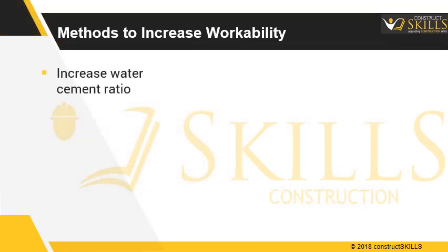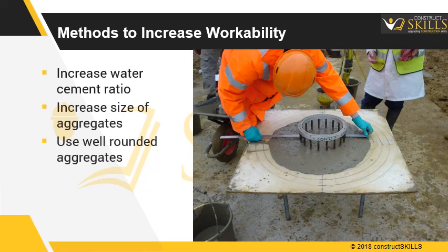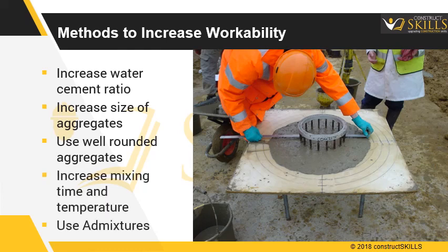Methods to increase workability: increase water-cement ratio, increase size of aggregates, use well-rounded aggregates instead of irregular aggregates, increase mixing time and temperature, or use admixtures.